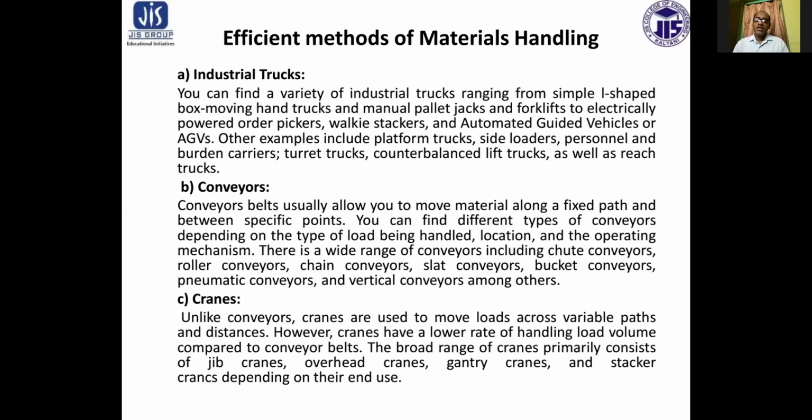Cranes. Unlike conveyors, cranes are used to move loads across variable paths and distances. Also, with cranes, heavy duty loads are generally moved from one place to another very efficiently. However, cranes have a lower rate of load handling volume compared to the conveyor belt. The broad range of cranes primarily consists of jib crane, overhead crane, gantry crane, stacker crane, depending on their end uses.